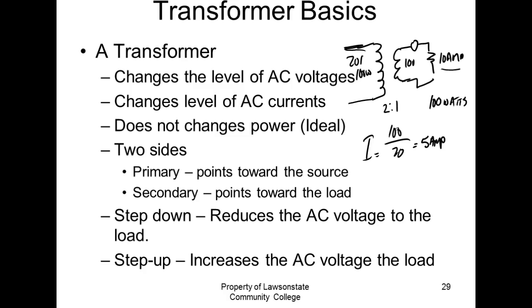You understand that? And you said, wait, in Ohm's law it says if voltage goes up, current goes up. But you're talking about over here on the load, we're talking about the source to the load. So yeah, if I was to double this 10 volts right here, this would go up, right? You understand? But we're not doing that. What we're doing is we're playing around with the source. So if these were 100% efficient transformers, when I flip this sucker on, TVA or Alabama Power would have to give me 100 watts because that's what we're paying for. We're paying for the work out here at the load, right? You understand? So transformers do not change power.